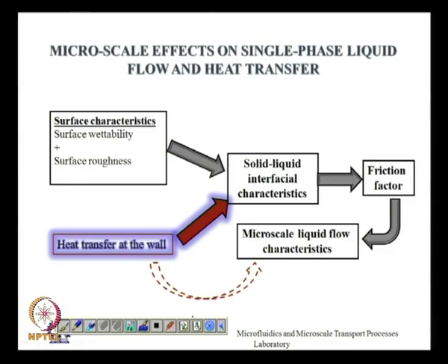So, the trend of research so far was create a new surface of some roughness, make it hydrophobic or hydrophilic, supply some amount of heat flux, let the bubbles form, heat transfer take place, and try to see what is the optimum, at which point you are going to get the maximum amount of heat transfer. So, the trend is for different flow geometries, different structures, when you are going to get the maximum heat transfer. But something else could be thought of, which I am going to show in the last few slides.